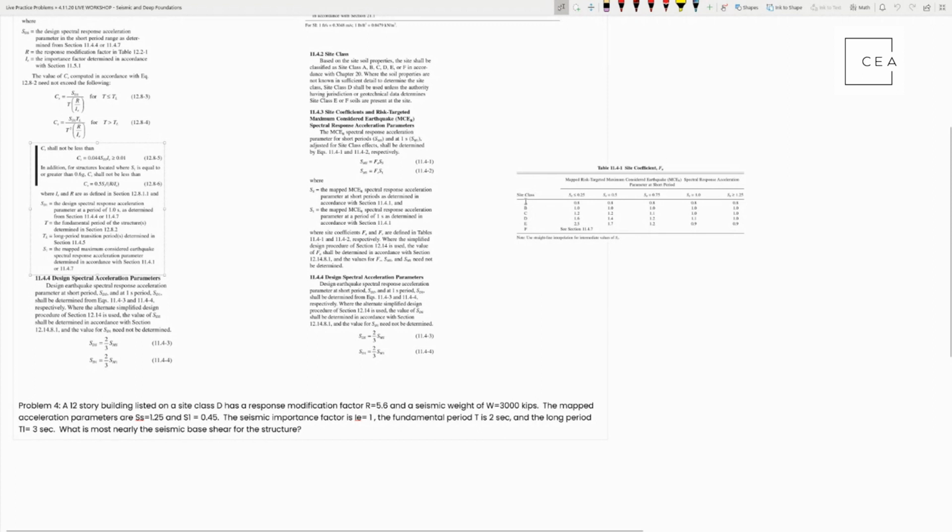So if you've been given a certain site class, which is dependent on soil conditions and such, you can go look up what your value should be. And you've been given these different values for what SS is, which is based on what comes from the map, right? So you go find an SS, let's say you're in class D, and you've got an SS of 1.0. If I'm reading that straight across, it should be 1.1.